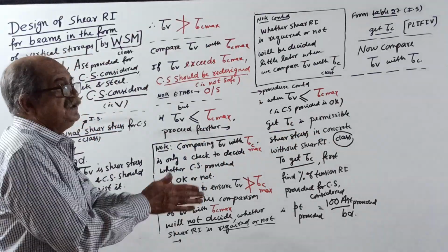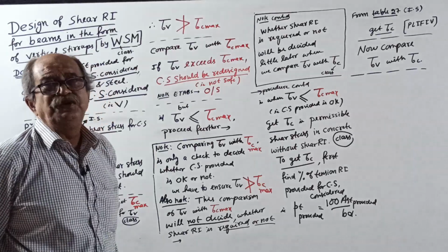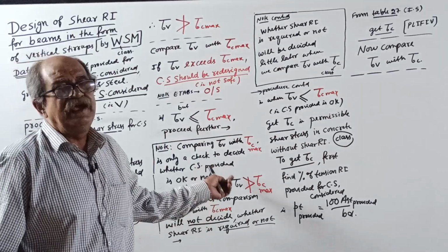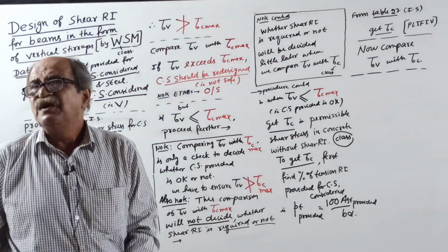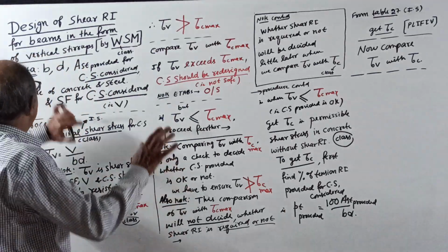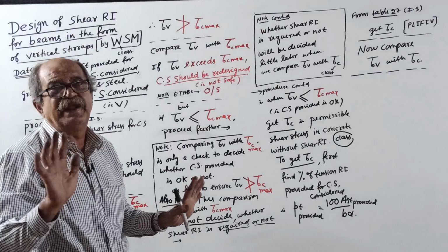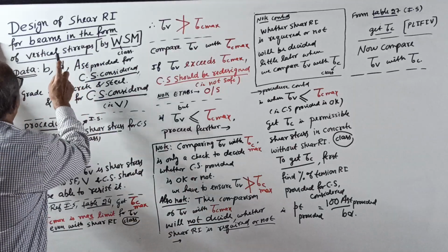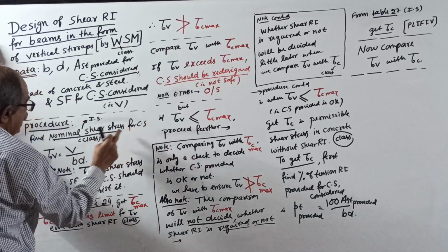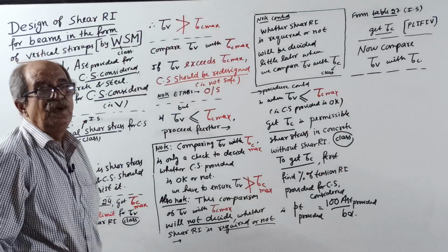Okay. Shear force V, there will be shear stress. Now, how is the distribution of shear stress? All that I won't discuss here, because I discussed it in the regular group. For them I give extra information about behavior. Now here, procedure to design shear reinforcement, that's all you are covering. Right now I am doing it with vertical stirrups. Okay. Find nominal shear stress for the cross section, tau v equal to V by bd.